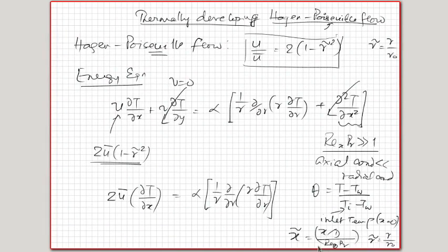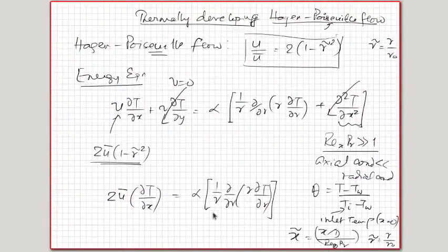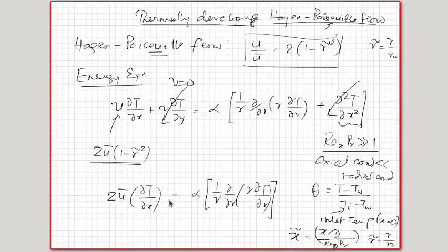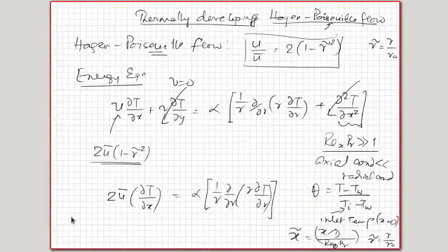And this Re_D of course you know is U bar, that is average velocity, multiplied by diameter divided by nu. Okay, so if I bring this alpha to this side and rearrange this expression, then I'll get, sorry, this 1 minus r tilde square is missing.